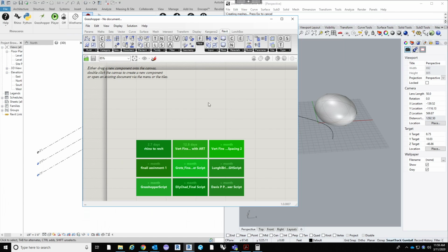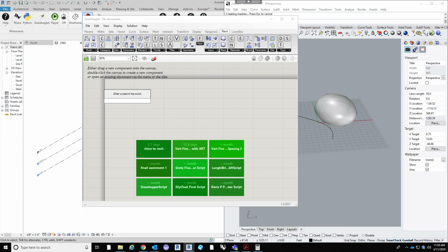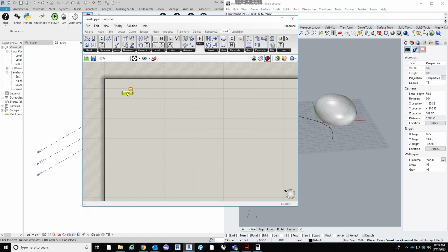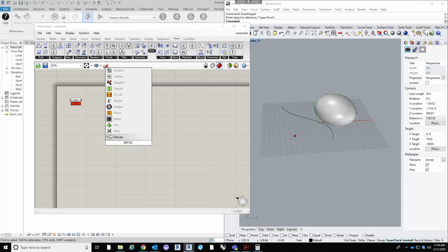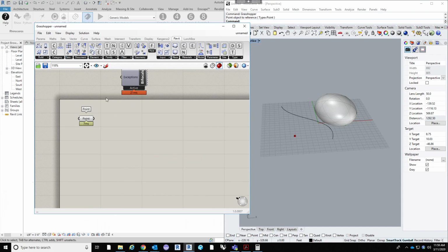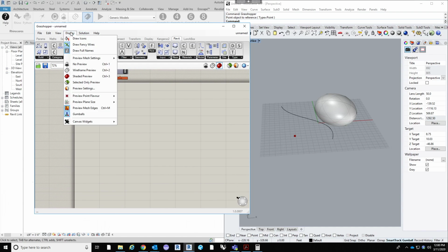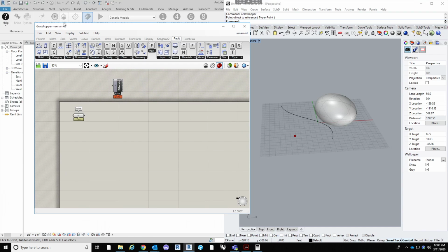So the first thing that we will do is, just like in a regular Rhino or Grasshopper script, we'll bring in a point. And to grab that point in the Rhino environment, right click, set one point, click that, and it gets populated in. And I actually have a new plugin that will help you guys, hopefully. It gives you a little bubble above that says exactly what those tools are, so I don't need to draw full names anymore. And then curve, same thing, set one curve.